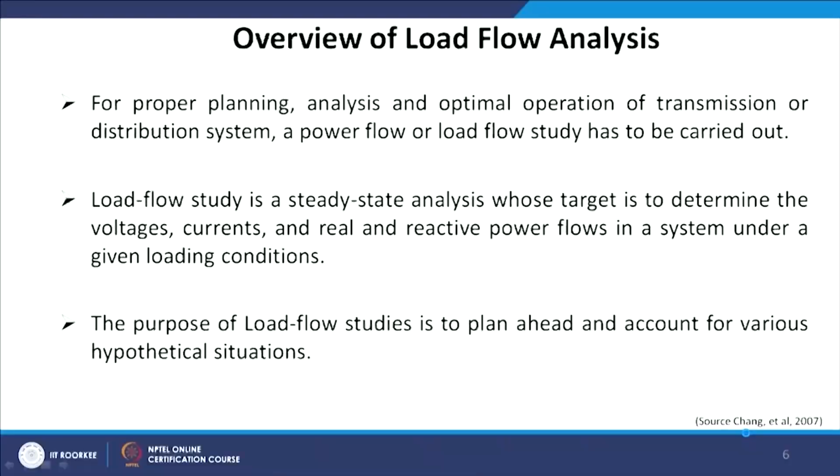So, if the loads are known to me, I must be in a position to determine the voltage at each and every bus, and the real power and reactive power flow in each and every line need to be determined. Now, the purpose of load flow studies is to plan ahead and account for various hypothetical situations. If the load scenarios keep on changing, how do I plan my system so that the voltage at each and every node does not violate the permissible variation, maybe 2%, 5% depending upon the utility?